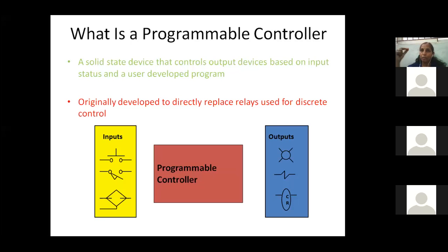Or for example, in a manufacturing industry, you connect this sensor on a conveyor where metal objects are traveling. This particular sensor is used to sense how many parts are being moved on the conveyor. How can it be done? It should be interfaced with the PLC, at the input module of the PLC. These are some of the symbols, like this is the common symbol for a proximity sensor, here for example at different voltages.